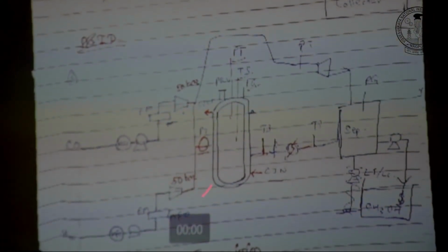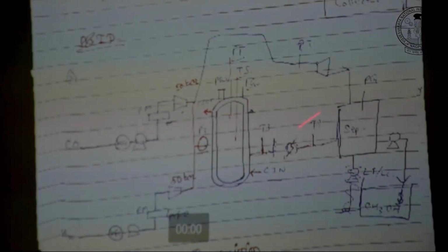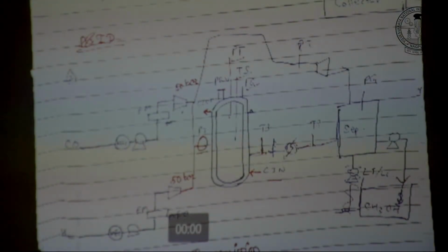The operating temperature of the reactor was 300 degrees centigrade, and we said you always extract heat at the highest temperature possible, and you could have done it with steam generation, right? So it's not wrong, it's not right, but that's how your 1895 euro per ton would have been 1500 euro per ton. That's how you could have brought down your product price.